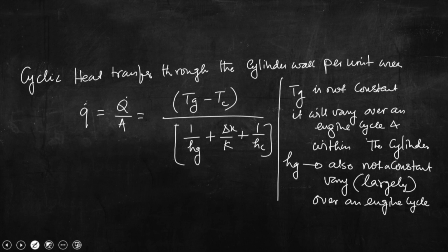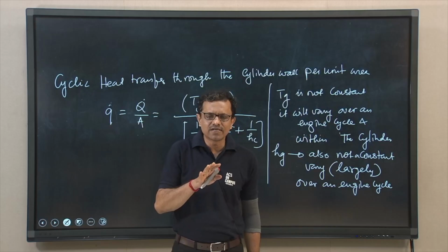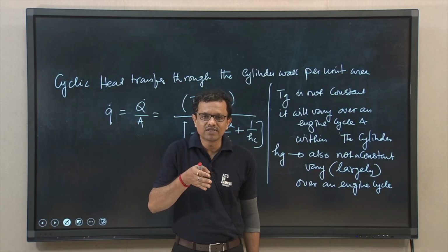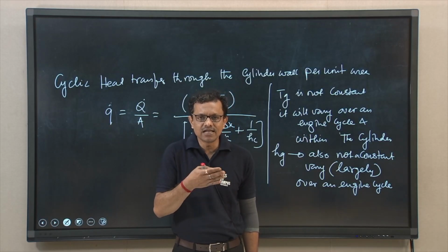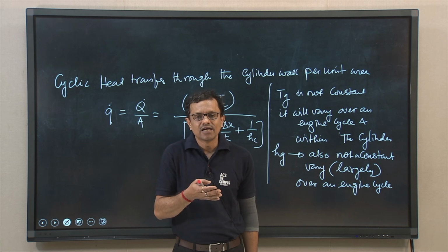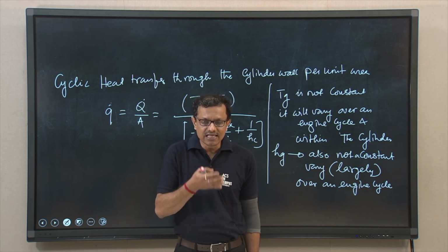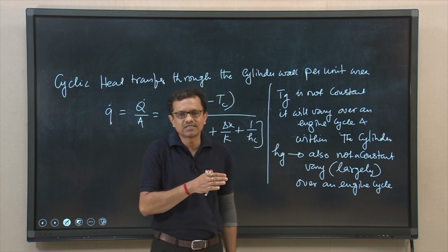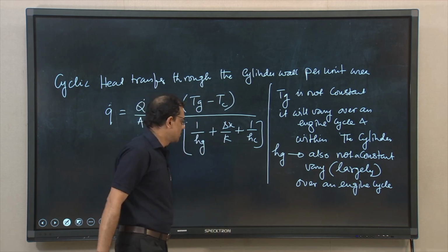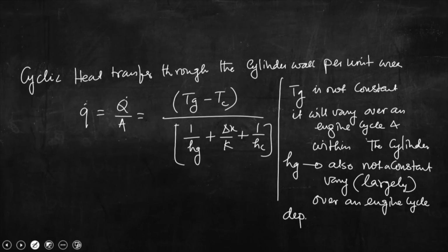Quite obvious, during combustion convective transport of heat will be there, and when combustion is completed, still convective transport of heat would be there, but during that time the convective heat transfer coefficient will not be the same as when combustion initiates, and it depends on swirl, turbulence and gas motion.